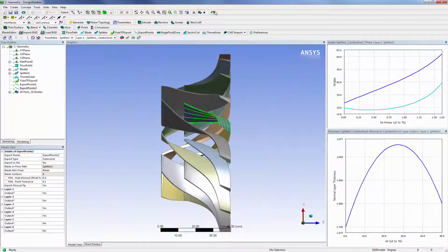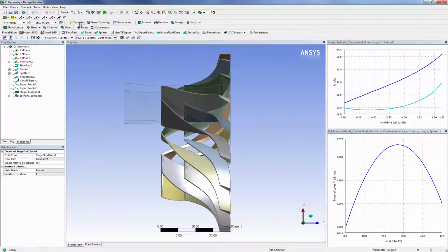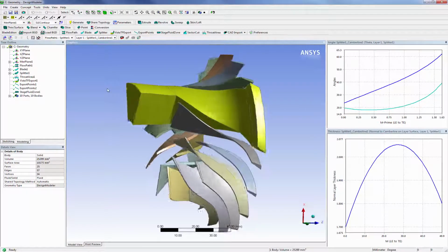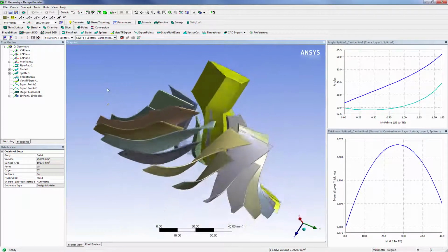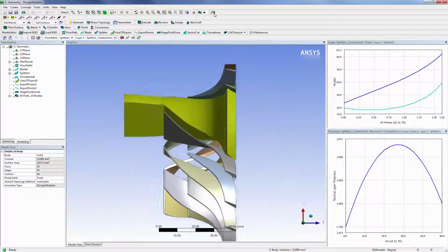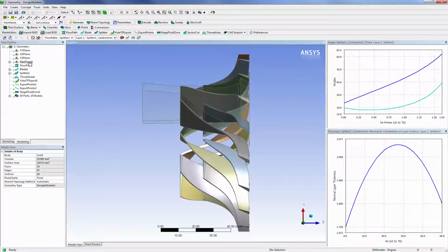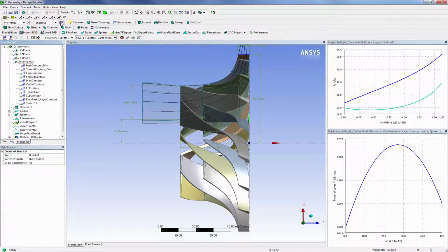If I need to specify a flow region for use in general meshing tools, I can create a three-dimensional periodic fluid zone corresponding to the region of fluid flow around a set of blades using the Stage Fluid Zone option. I can also use the sector cut feature to generate a three-dimensional sector of the solid hub that is aligned to the staged fluid zone.